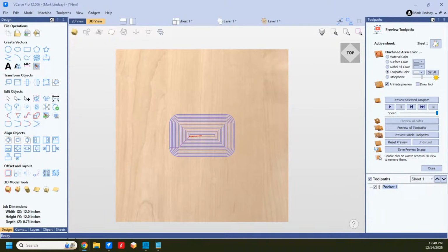When you're first starting out, you're trying to learn everything at once. You have to be able to learn how to design, how to mount the material, how to use the machine, what it's capable of, what you're comfortable with, what the material is going to allow. So I recommend, when you're just starting out, half the diameter of the end mill as the pass depth.